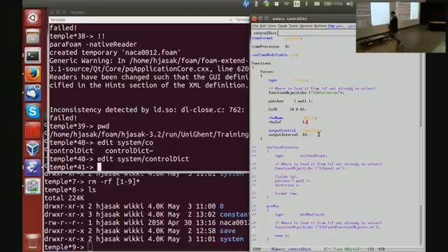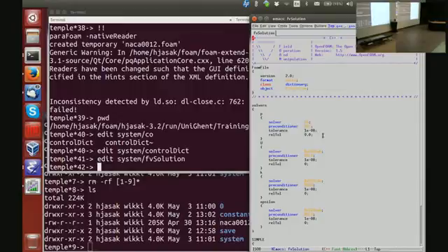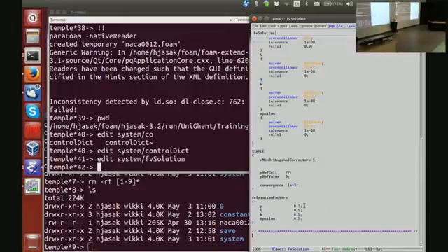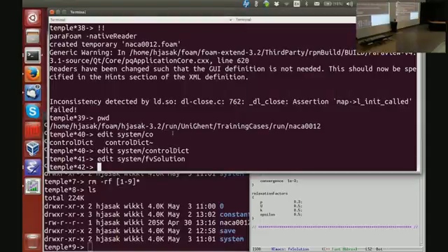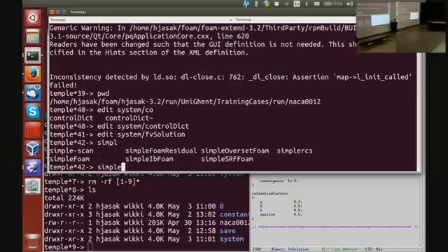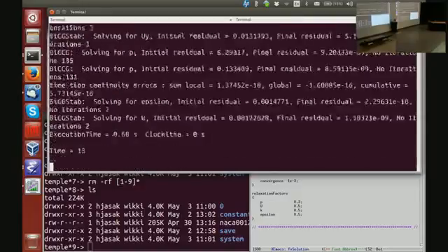The solver is simpleFoam, and the other thing that I want to show you is the relaxation factors. 0.3, 0.5, 0.5. Typically you can run 0.3, 0.7, 0.7, but usually with these tutorials people mess about, so I keep it a bit more conservative than necessary. simpleFoam, pipeT log.